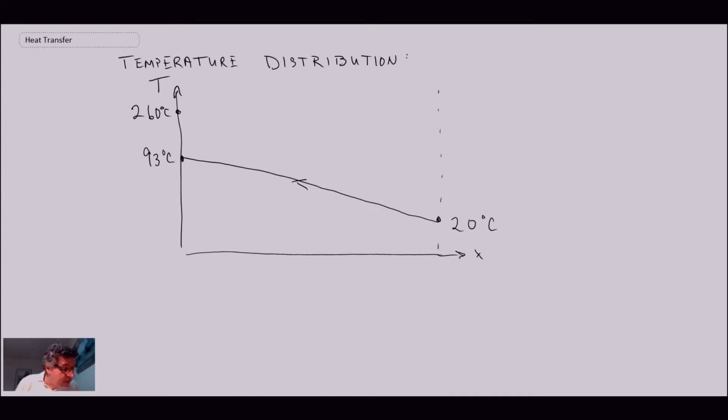Okay, so when we're looking at the temperature diagram, we can say this is TC2, this is TC1, and this is TH1. Now, we don't know the exit temperature of our hot fluid stream, so it's going to be somewhere in here. So we'll put question mark equals TH2, and then that means that we're going to have some kind of line drawn, and the fluid stream will assume that it's counterflow going in that direction. So that's a bit of a problem. We don't know what that temperature is on exit. Let's take a look now at what equations we have that we can work with.